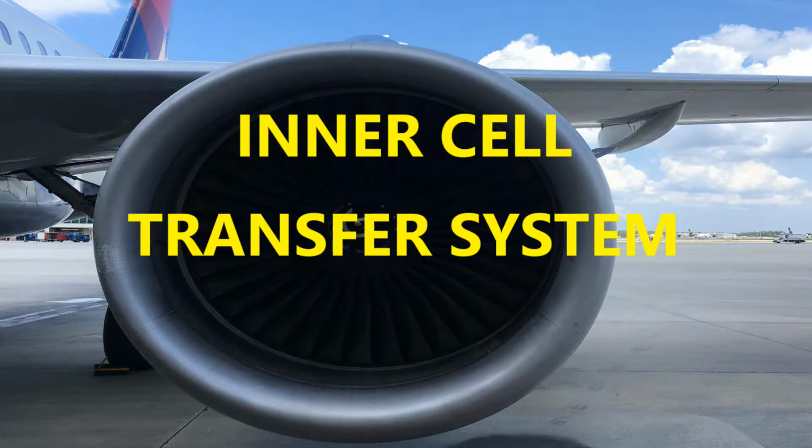Okay, so let's look at the main pumps. Remember I said that there's a pump for each of the fuel tanks, and I was also telling you how with the center tank, if its pump goes out, that's just it. There's no backup system for it to distribute fuel to the engines. Whereas with the wing tanks, you do have that ability. It goes into a suction feed essentially. The engines are going to make sure they get that fuel from that source.